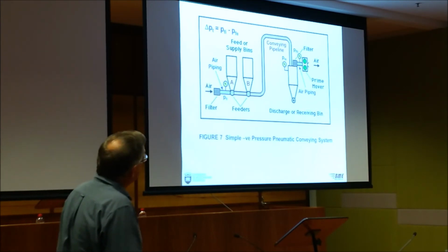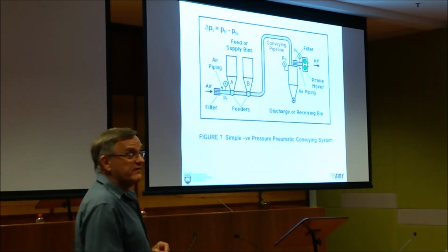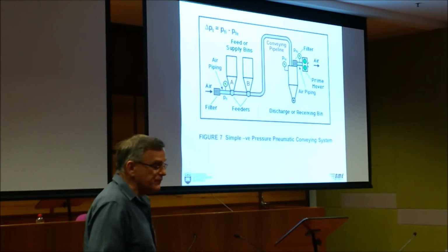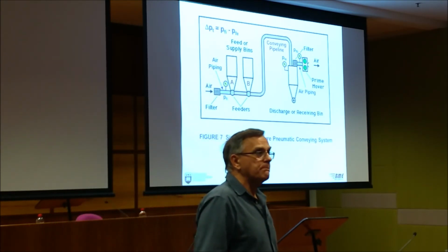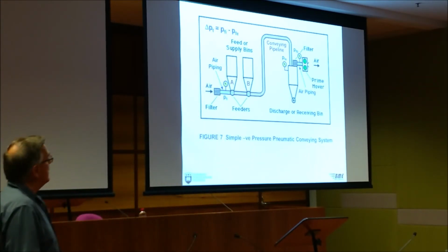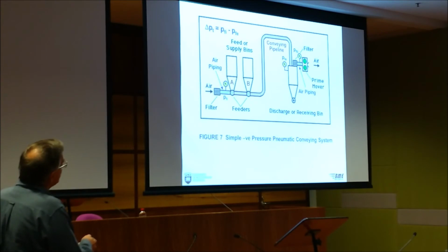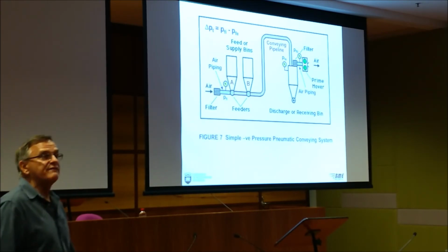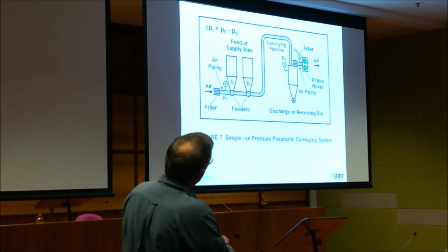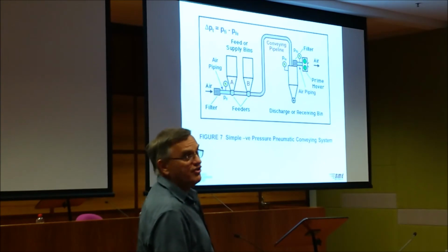Alright, but that's not the complete story as far as pressure is concerned, because generally with a vacuum system, the pressure drop across the filter is more. It could be 10 kilopascals. And so, let's say this is a blower, we might say that that's the inlet vacuum pressure of the blower. We put a pressure gauge there. This might be reading -20, that'll be reading -30.